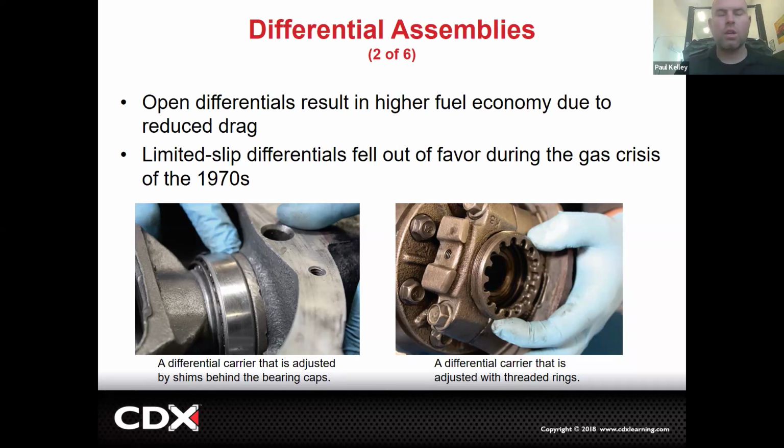It sucks. The default, if the car doesn't specify, it's got an open diff. A lot of times you have to pay more to get the LSD. Like on a Silverado, or generally on a GM truck or SUV, if you want the limited slip, you have to get that option, and it's called the G80 option, which we're going to cover not only in this presentation but as part of another discussion, right? So you can order it with the LSD.